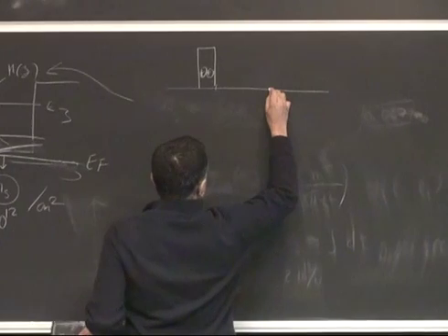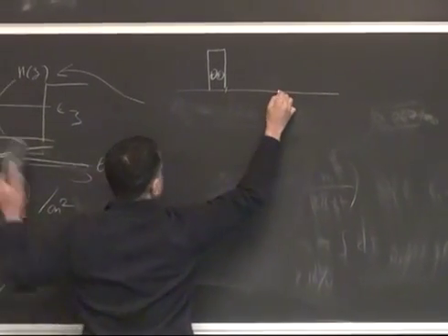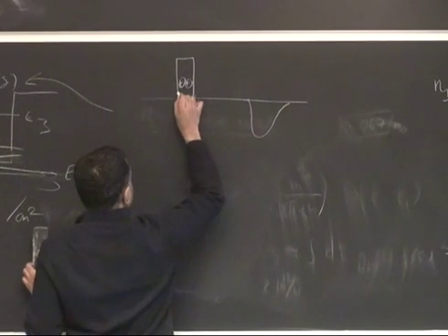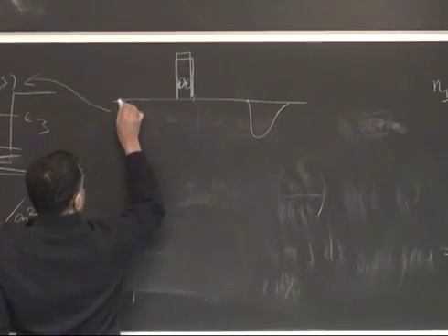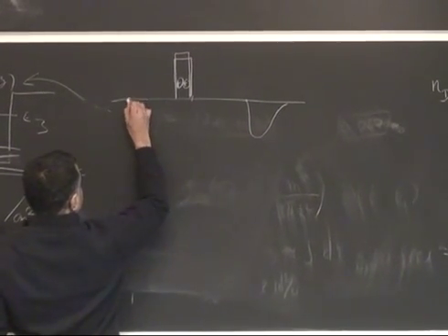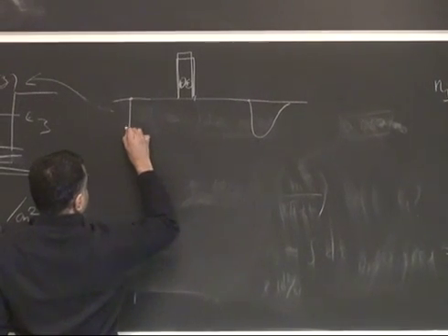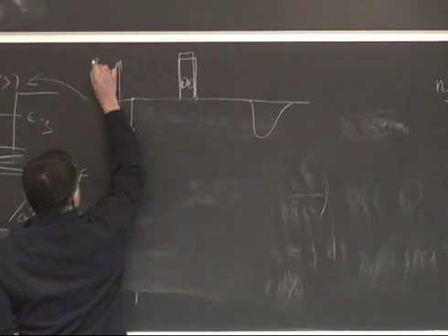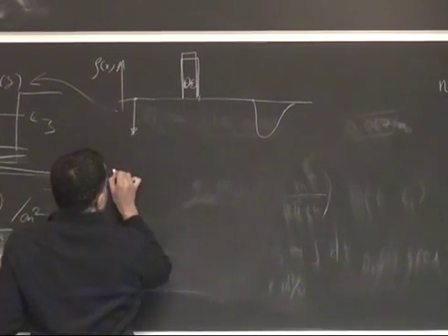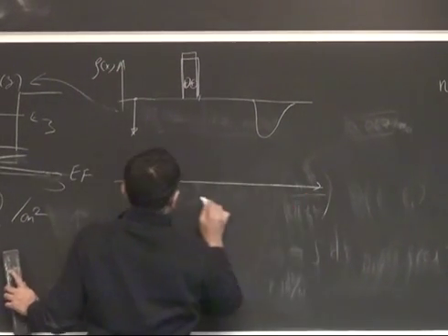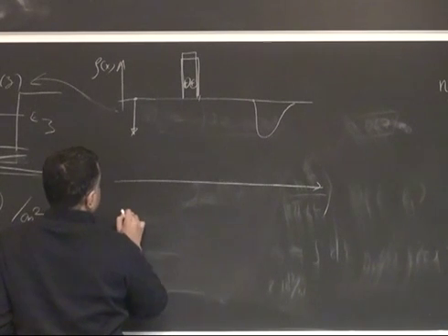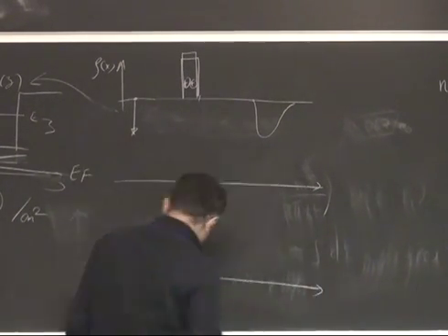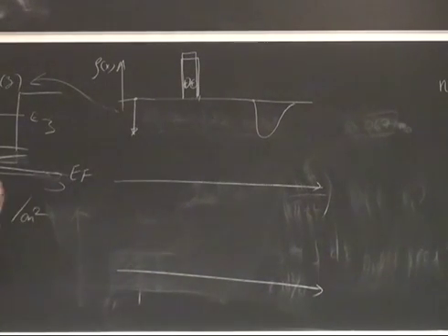I have a mobile electron gas in the quantum well, which we just sketched, and this can be large. The rest of the charges are in the metal, and they are negative. So this is your charge, and I think you can now sketch the electric fields. Let me do that analysis now. This is how we're going to calculate the threshold voltage of this transistor.